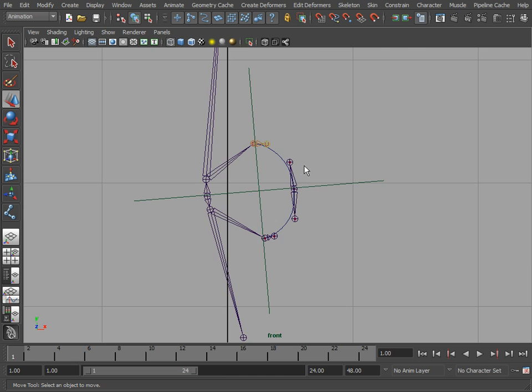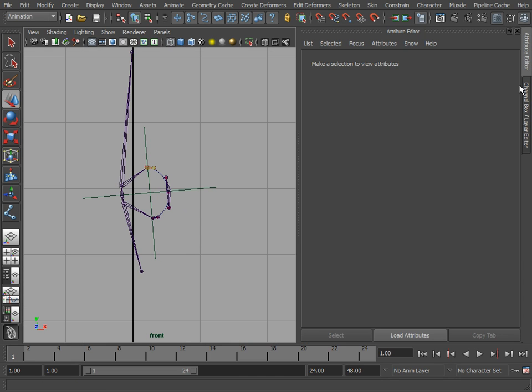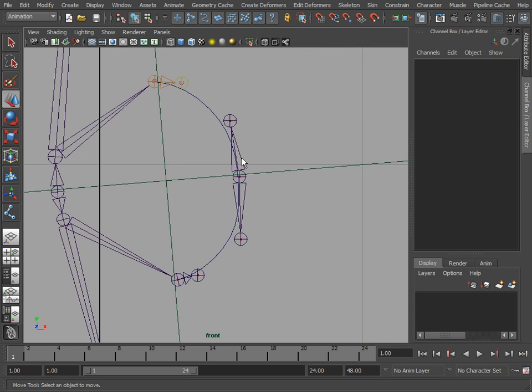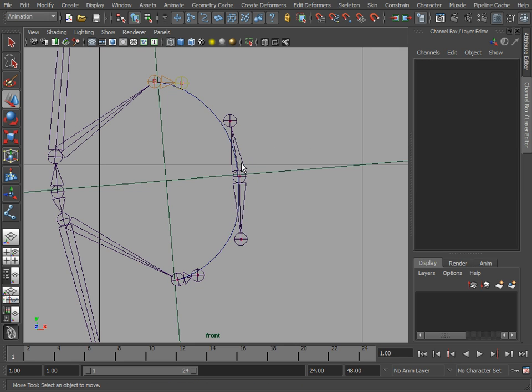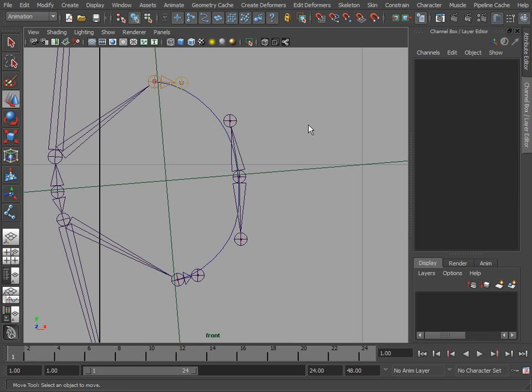However, we could do that, but just for a cleaner setup, we want to create a curve as a handle, because one thing about the joints here is that we cannot freeze the translates of the joints, and if we move this joint, we're never gonna be able to find the default position.